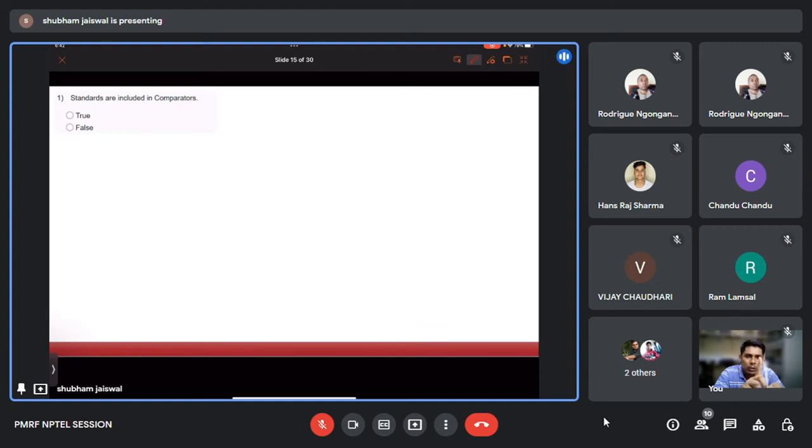If some fluctuations are there, it will not be the zero position. So that's why we will not get the correct measurement. But in deflection type, what will happen? This pointer will deflect based on the input that is being measured, or the input torque exerted on it. So if there are some minute changes or fluctuations in your measurement, this will be detected by our deflection type.